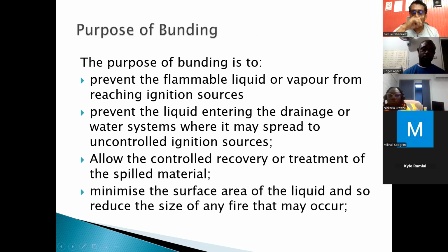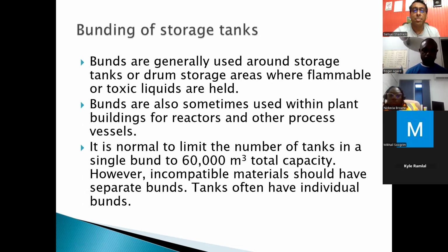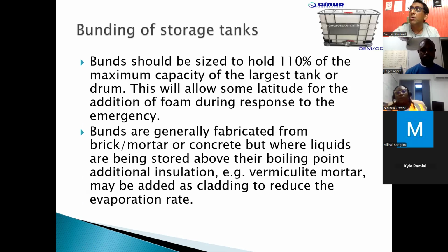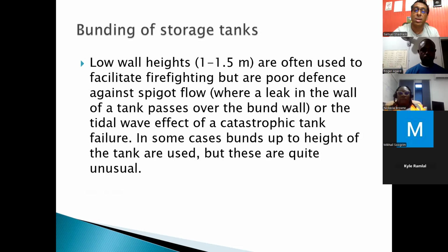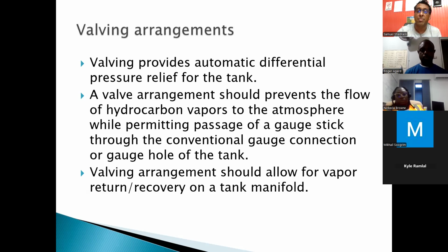So the purpose of bonding, we spoke about that, is to contain the spilled oil, right? Bonding around storage tanks must be able to hold 110% capacity, which they do, but you can't really hold more than that in the event of a flood, right? 1.5 meters high is not high. That's why I say it's a series of pits. 1.5 meters is less than 2 meters or 6 feet, so this is less than 6 feet. That's less than the height of a door. A door is 7 feet. That's why you need a series of them, right?